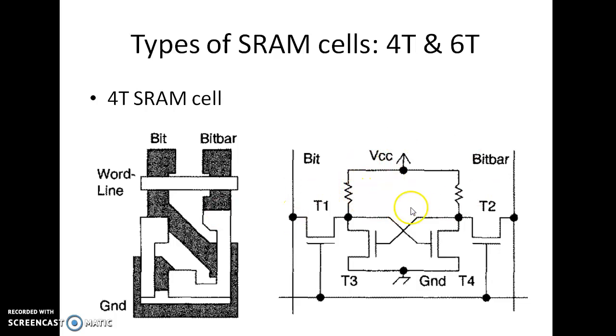So the resistor can be replaced with a MOSFET, which occupies very less area. And the advantage of using a MOSFET is, you know the concept, right? If you change the VGS and VDS, the resistance of the MOSFET gets varied. So it also acts as a variable resistor. So without refabricating the MOSFET, you can change its resistance by simply changing VGS and VDS. So this is an advantage of replacing a resistor with a MOSFET.